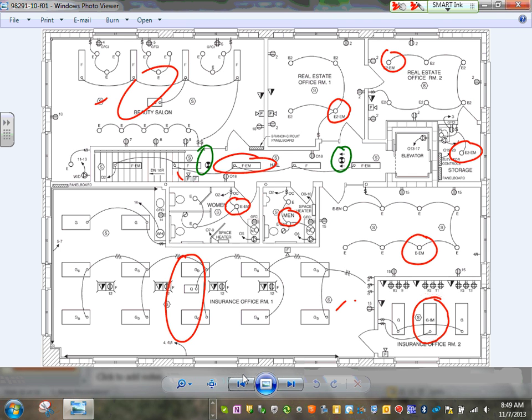I will walk you guys through the egress path for the project that we have. Typically the architects establish the egress path in the building. I can tell you, you can guess all the hallways. Almost all the hallways are egress path because people have to go through them, right? And then in open offices, you have to establish an area in the middle. That's where people come out into the middle, light that area for them and channel them through the hallways all the way to the exits of the building. That's all you need to light.